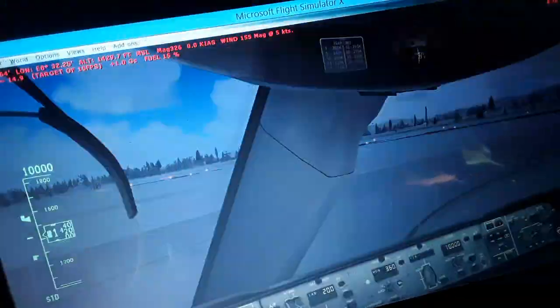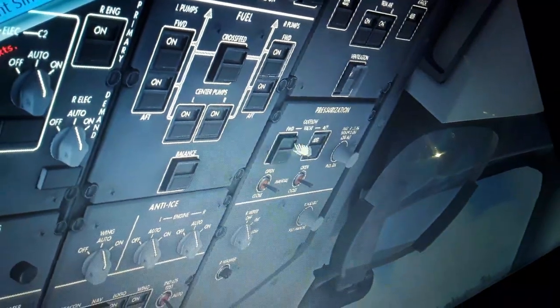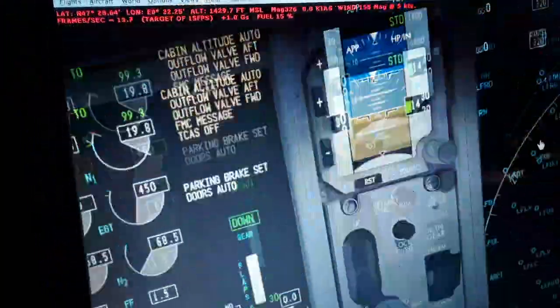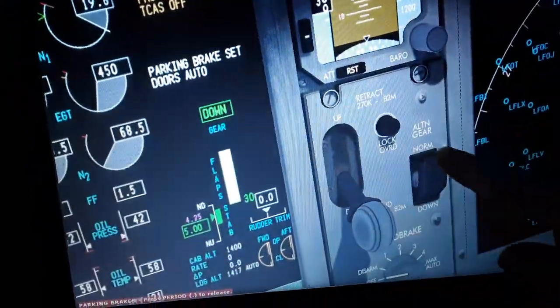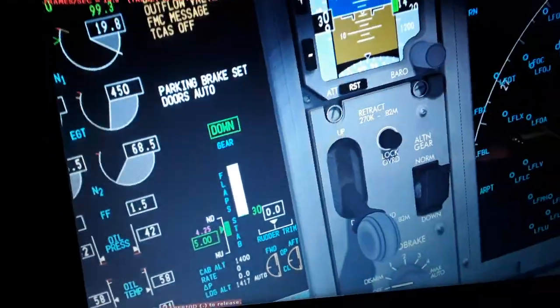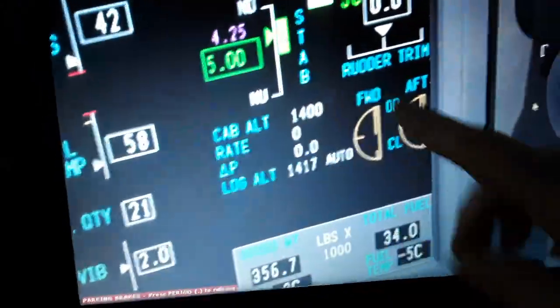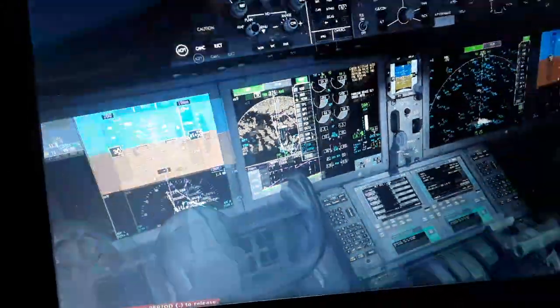also pressurization. Over here you see cabin pressurization. We use it in the manual mode. You will see what will happen, what will display. The outflow valves are in manual mode now. So we have also landing gear here, alternate gear, autobrakes, also displayed in the EICAS, not related to the engines directly. We have the outflow air from the 5th and 9th stage. So the FADEC can control the outflow valves and air pressure from the 5th and 9th stage from the bleed, from the bypass from the front fan.